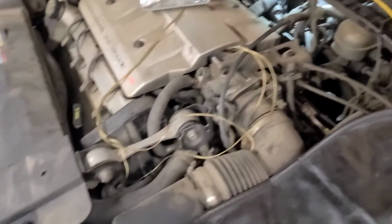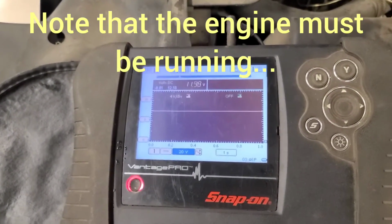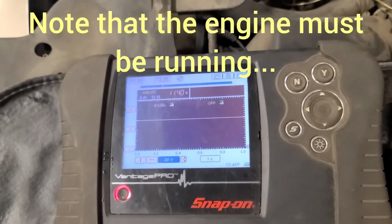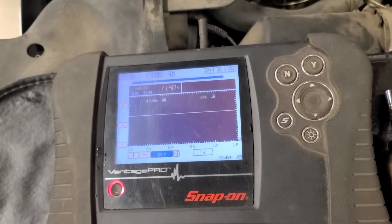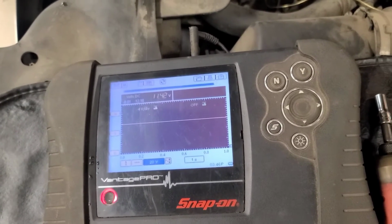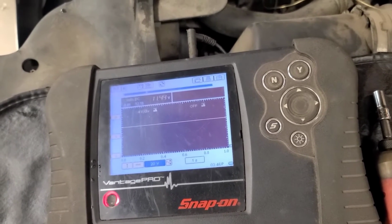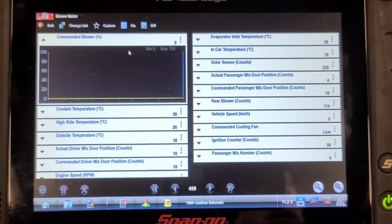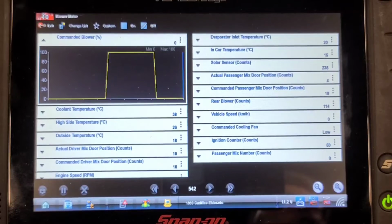And I would suspect that it duty cycles it or pulls it to low to control the transistor in there. But it doesn't change when I turn the heater fan up and down, and it doesn't change when I command it on and off with the scan tool. So I'm pretty sure this thing's going to need a blower motor, but I'm not 100% certain of that. So here's a bidirectional control of the blower motor. If I command it to 100%, it should run full blast and then off. Now I watch that voltage on the voltmeter, it doesn't change.